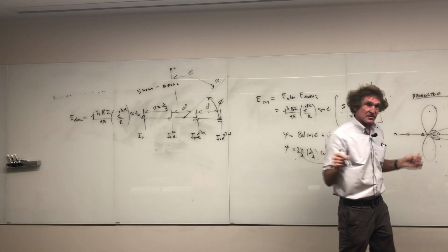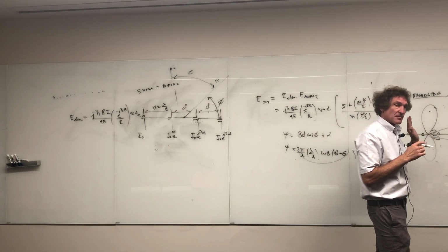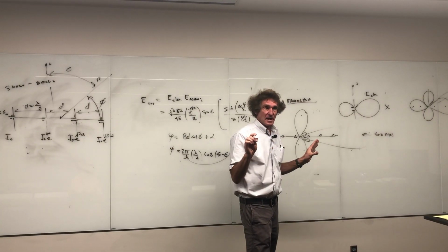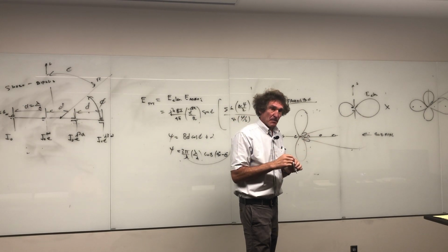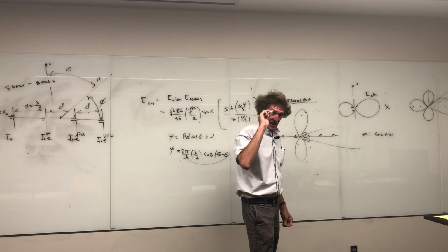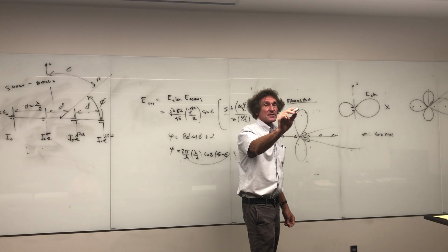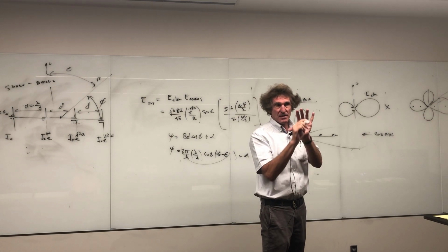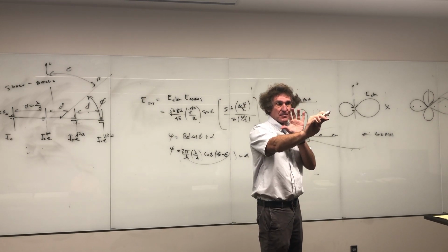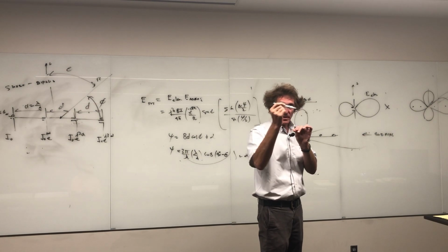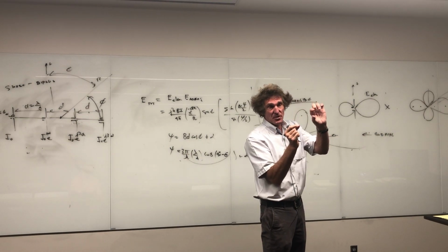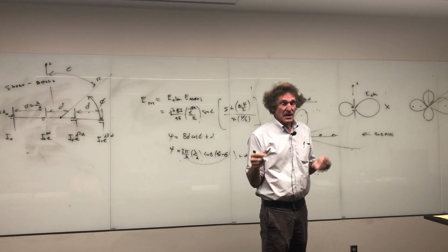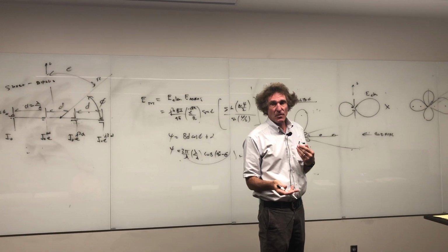I don't want to spend a lot of time on this right now, but I'm just going to give you an appreciation for this. There's another term you're going to hear over and over again. It's called the bore sight of the radar or the antenna. Bore sight is in the main beam. The way it's directed is called a bore sight. For instance, if you have a standard parabolic dish antenna, bore sight is perpendicular to the dish. If you have a dipole, like this short dipole, they don't even usually use the term, but bore sight would be perpendicular to the length of that dipole. Got me on this, class? That's the terminology that you have to be aware of.